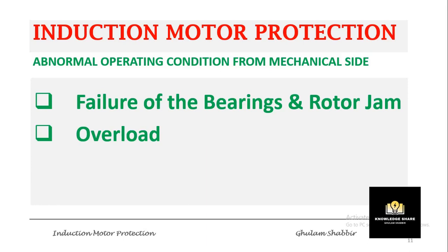Thermal overload relays offer good protection against short, medium and long duration overloads, but may not provide protection against heavy overloads. Long-time inverse overcurrent relays offer good protection against heavy overloads. A combination of the thermal overload relays and the overcurrent relays provides complete thermal protection.